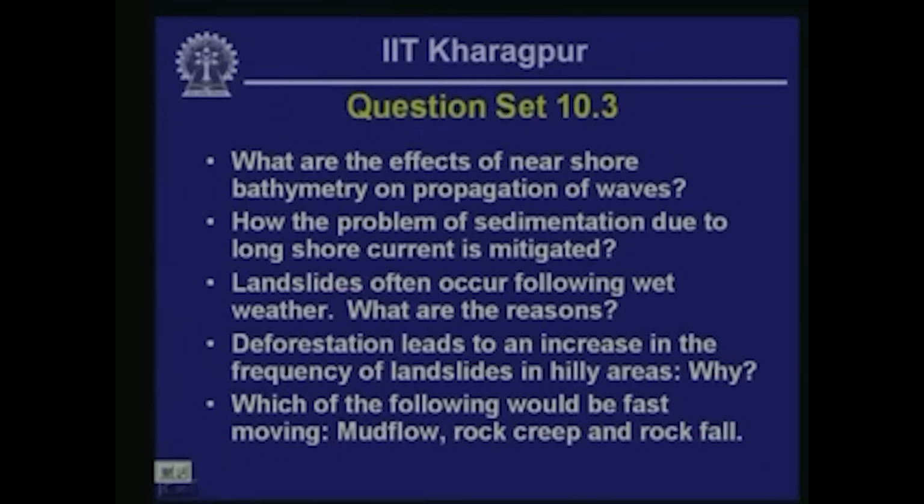As I discussed in the previous lesson, if you have a protrusion of a landform jutting into the water, and the bathymetry also reflects that kind of onshore or subaerial topography, then that area is going to be affected by refraction and focusing of the wave energy.